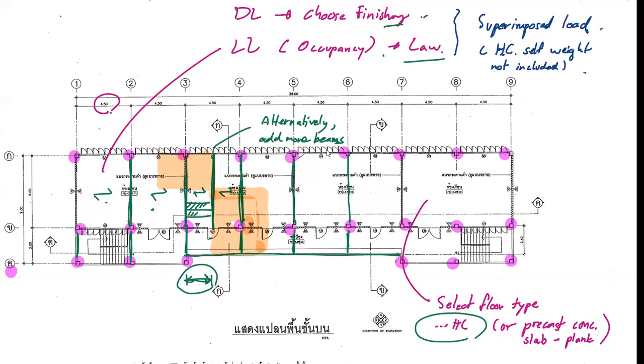Because there's nothing you can do but the floor, the requirement is there. You need to select the floor type so that it can hold the load. But if you choose to use the floor as part of the composite structure, the size of the beam can be further reduced, and may I add significantly as well. But if you choose to have the composite structure, what you must make sure that you have is the composite action between the concrete floor and the steel beam. And by that, we will add the shear connector.